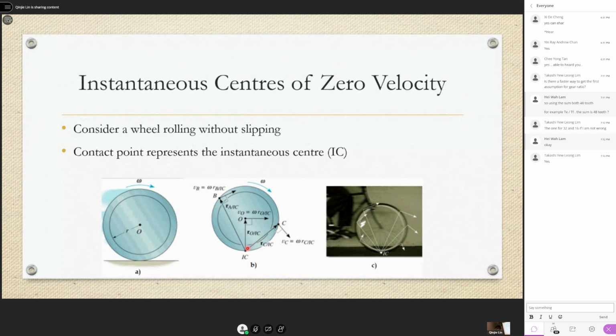And same for C. A point like C, if you draw, C will be traveling towards this direction. It's not going down, it's not following the wheel, because at this moment this whole thing is also moving to the right. So C will be going in this direction. It's trying to move down, but also forward at the same time.